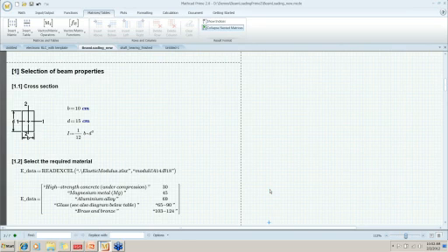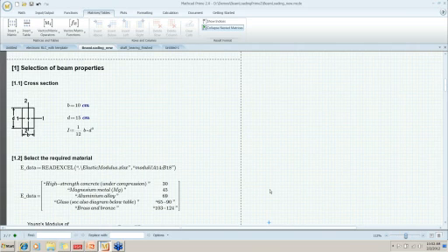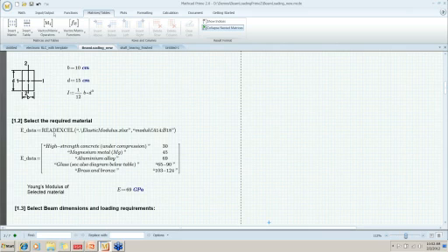Okay, and so the first thing we're doing here is we're reading data in from Excel. Mathcad Prime has some new functions called Read Excel and Read CSV. And so you can read data in from Excel. You just give it the path to the Excel file, and you could even give it the specific range of data to read in, and the worksheet.